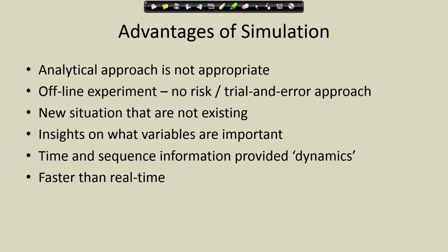But the Highway Capacity Manual, over time, recognized the limitation of not considering stochastic variability. I mentioned there's a left-hand bay that can hold maybe 5 cars or 10 cars, whatever you have there. And when demand exceeds that storage capacity because the wait time is longer, then it has a spillover problem. And no equation can model that properly.